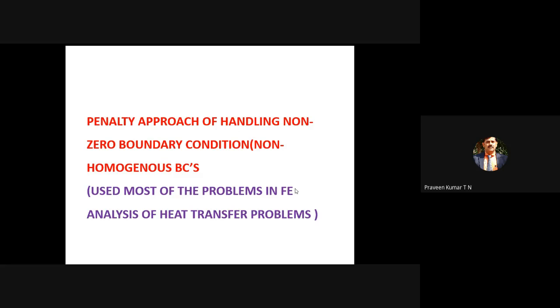The other end of the steel rod is exposed to the ambient temperature, that is, when x is equal to L, T is equal to T infinity. When x is equal to 0, where the thermocouple is mounted, the temperature is known and is not 0 there. So we cannot say that the temperature is 0 Kelvin or 0 degrees. Those are the extreme cases.